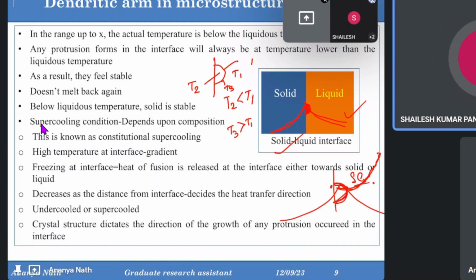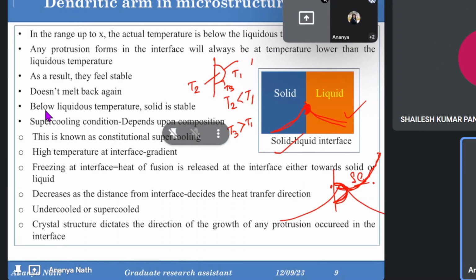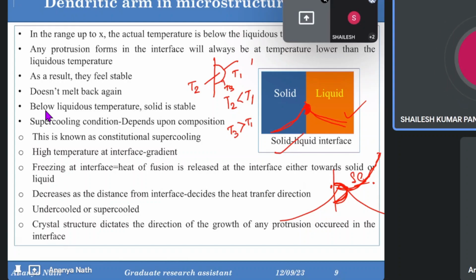So how can we relate these concepts from your point of view, ma'am, as you were discussing? In the case of supercooling, high cooling rate or low cooling rate, what is your question? Okay, take the example that we have a high cooling rate. If our cooling rate is high and we are cooling below the melting point temperature, then in the diagram shown in the lecture, delta G is negative, meaning GL is greater than GS.